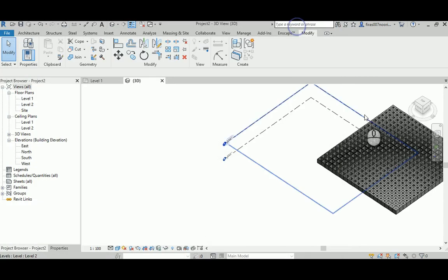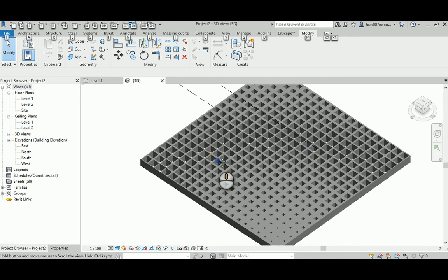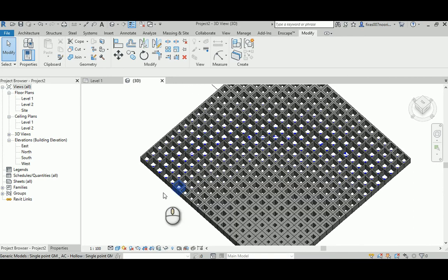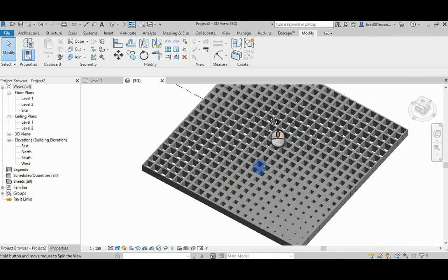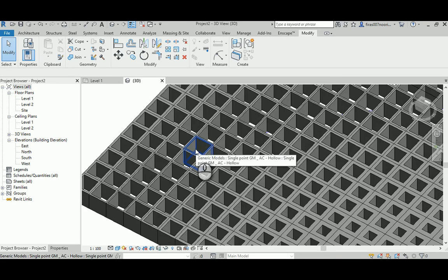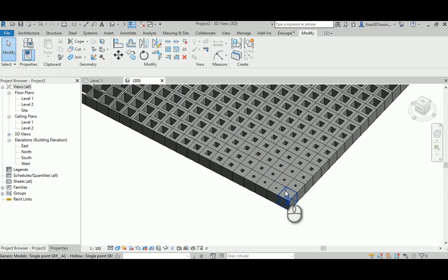So if you zoom in now, you will see everything is perfectly placed. You see the line now? That's the line, and the closer we get to the line, the adaptive component just gets wider, and whenever you go further away from it, you're going to get this smaller. I think that's really nice to do in Dynamo.